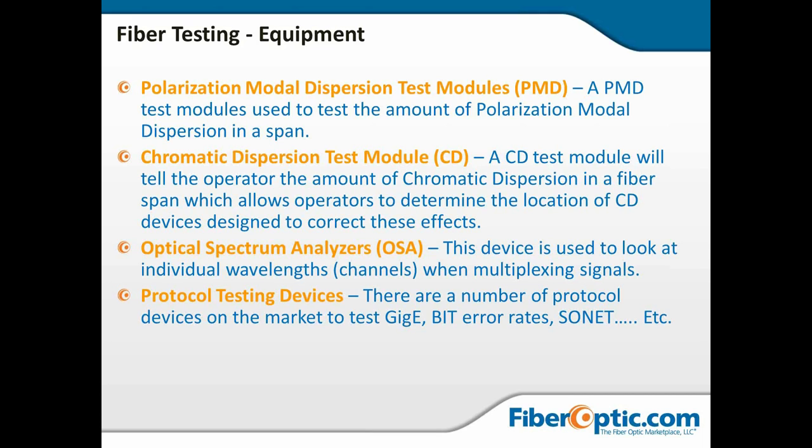Chromatic dispersion is pretty much under control. We can handle that. We can use compensation coils or compensation modules. We want to measure it sometimes to make sure that we match up with engineering, but it's linear, it's engineerable. You can get the amount of dispersion per wavelength from the manufacturer of the fiber when you're purchasing it.